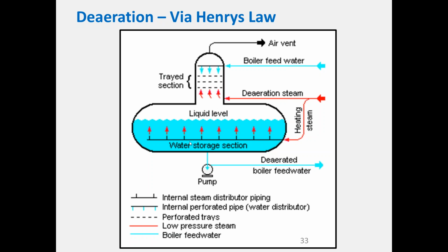And that's fine. Now, in the good old days, when we invented steam trains, the logic was that any oxygen is bad. So people went way out of their way with deaerators and dosing chemical oxygen scavengers to try to get the oxygen to zero, because it was thought that any oxygen is bad in any plant. Now, we've learnt a few mistakes around that, and we've discovered that some of that logic is wrong. If the plant is constructed out of all ferrous materials, it's all carbon steel, actually having zero oxygen is bad, and we actually want a little bit of oxygen present in the water.